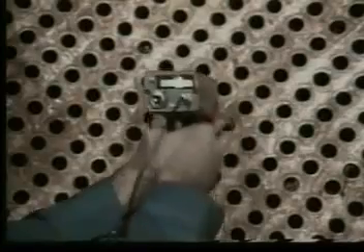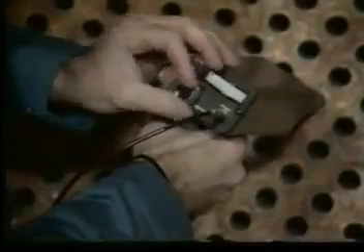When the loudest area is found, scan around in a star pattern to ensure it is louder and of a different sound quality than the surrounding areas. Mark the loud tubes with cork plugs. A natural progression from one zone to another will be noted by a change in the meter reading.